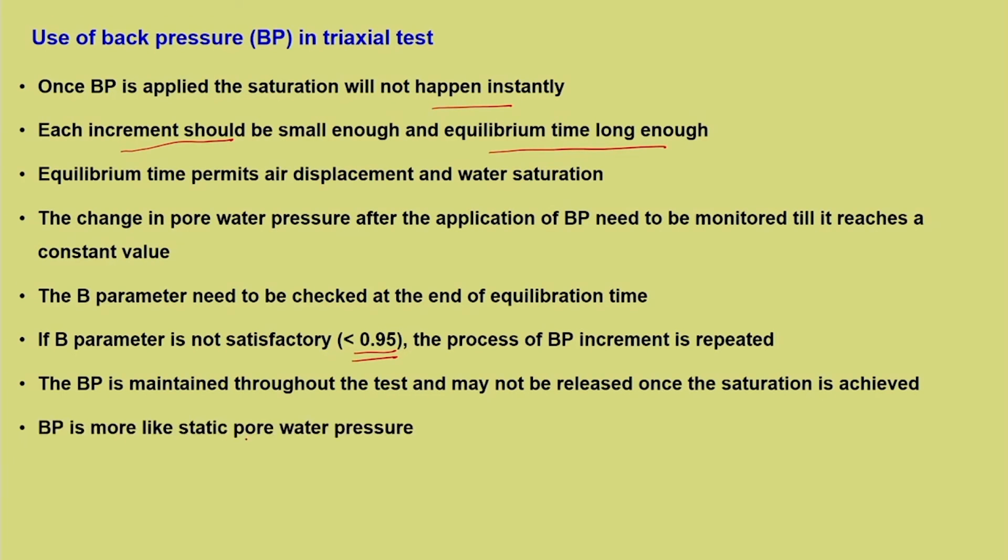So, back pressure is more like a static pore water pressure. We have seen what is a static pore water pressure. Only the excess pore water pressure brings about volume change in the soil mass or densification in the soil mass. This we have seen. So, here back pressure will not bring about any such changes. So, it is more like a static pore water pressure.